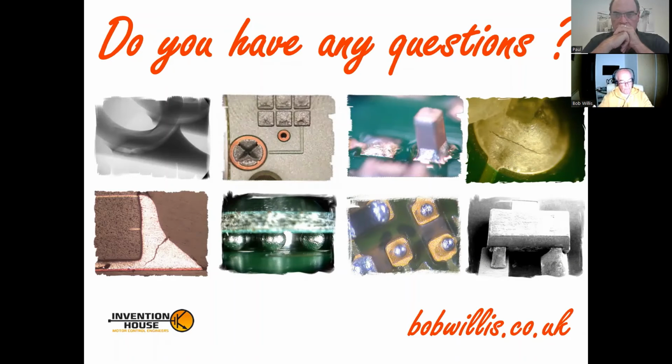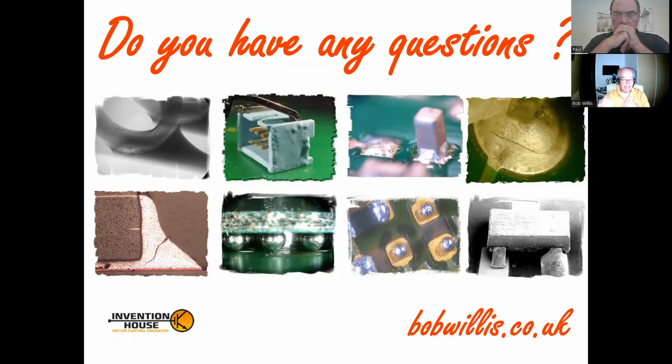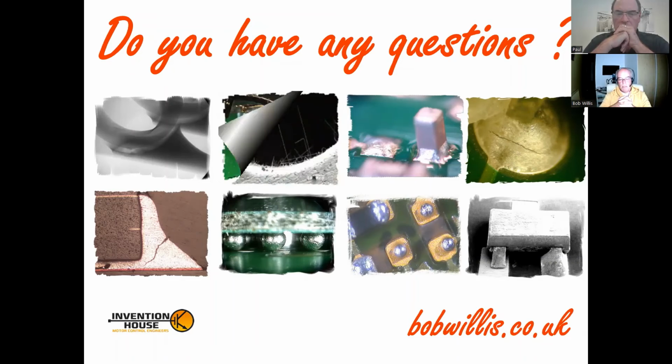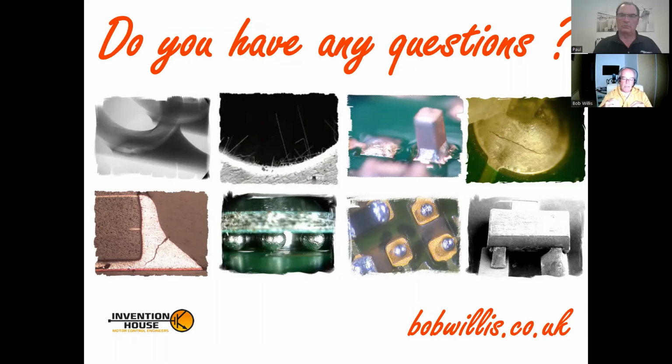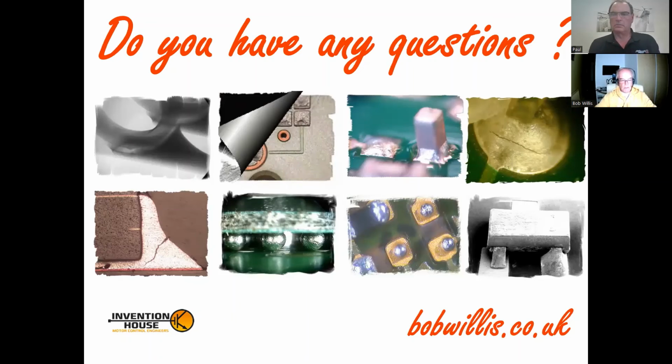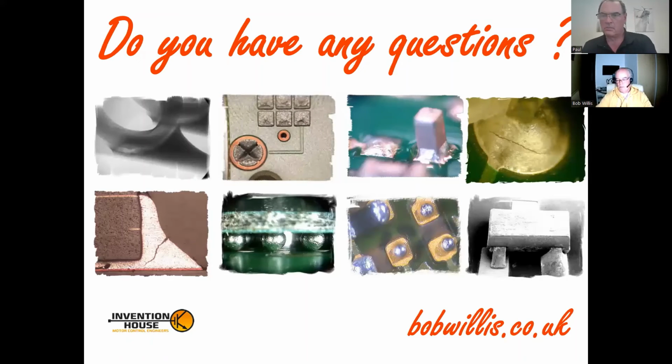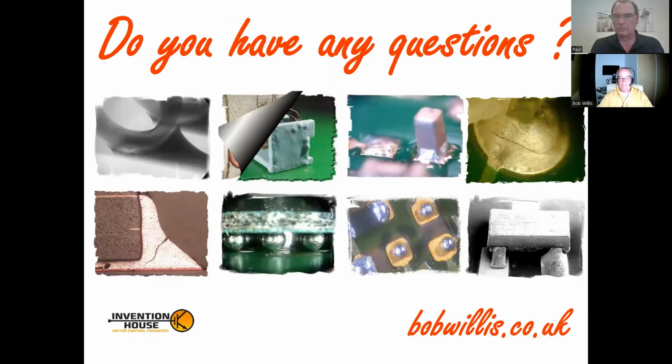As you refer to, I'm good at trick videos or videos to explain things. I've never been able to create that situation myself. But in theory, if you have voids between terminations, but if you've got voids in conformal coating in the bulk area, on the surface of the solder mask, on the top of a component, that is just, in my opinion, never going to cause failure.